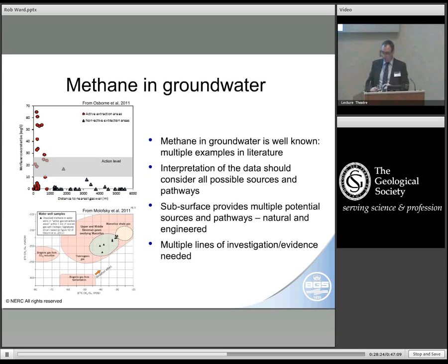And as Mike said, this paper is very controversial, and Richard and others have written rebuttals about the paper. But clearly these data show that you can get high methane concentrations in groundwater, and this grey bar across here is the action level. So we're saying that concentrations up here, if measured in water, could be the source of problems if that gas builds up in a confined space.